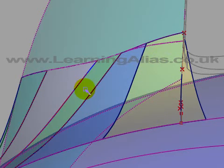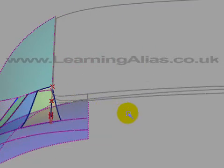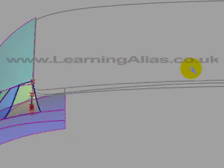And in fact these 3 patches are very difficult to control. These 2 are very easy, because here you're going round a curve. So what I've done is I've put a degree 5 curve, aligned it to that curve on surface there, and then just brought it up here. But I haven't just done that, I've also made sure that it's going to be curvature continuous in this direction.